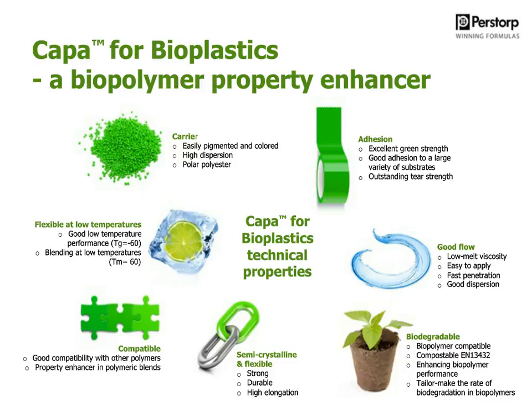Capa can also be used in hot melt adhesives. It has a very good adhesion to several different substrates, and thanks to the low melting point, it's also easy to work with and apply. And the higher you go in temperature, the higher the flow of the product. We also have a wide range of products with different melt flows, which will contribute to this.